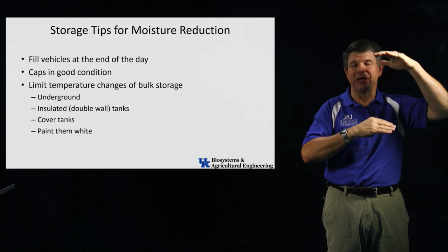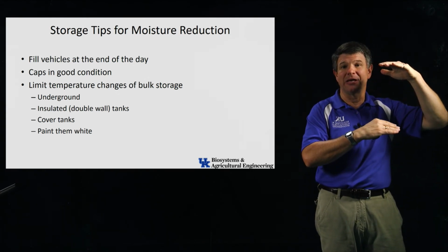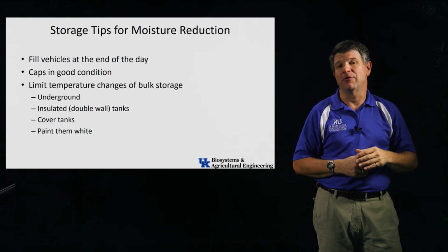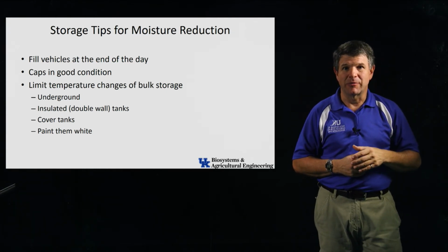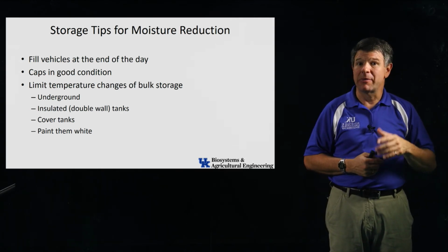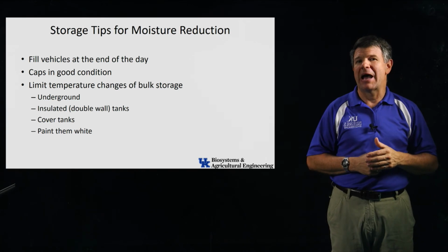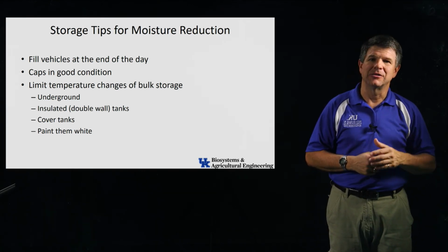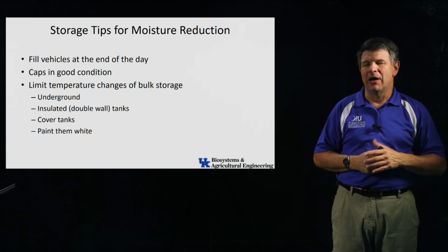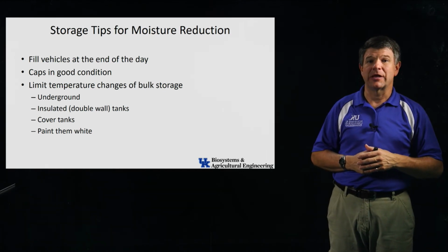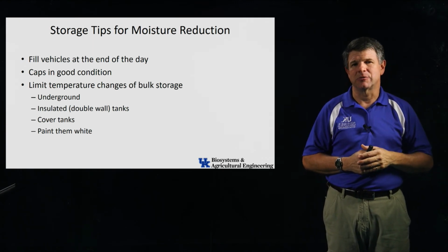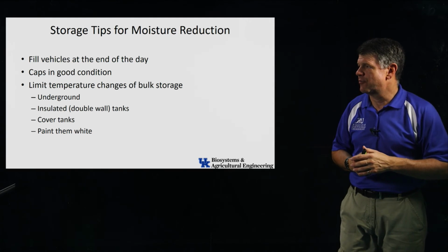So all that headspace above the fuel in the tank is going to be a potential place where we can get a lot of water into our fuel supply. And so that's why we tell farmers, hey, I know it's extra effort, you're tired at the end of the day, but when you come back from that trip, fill it up on the way back into town, and you're not going to get as much water in your vehicle. Most of our vehicles can compensate for that pretty well, but especially on farm vehicles, and especially in the wintertime on cold days when you're getting lots of temperature swings, that's when we can have some trouble with water in our fuels.